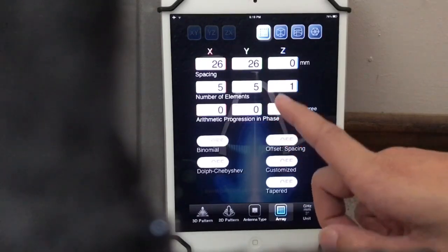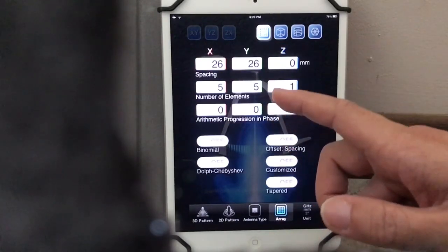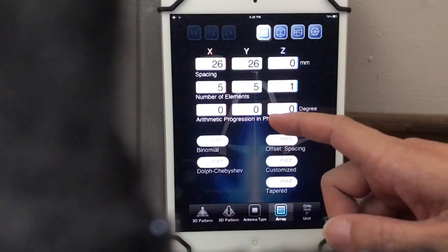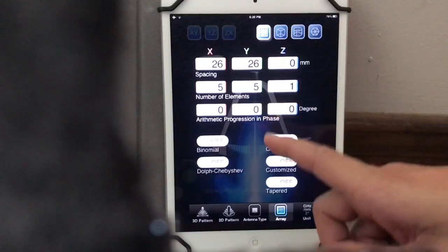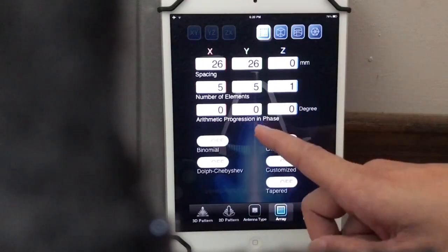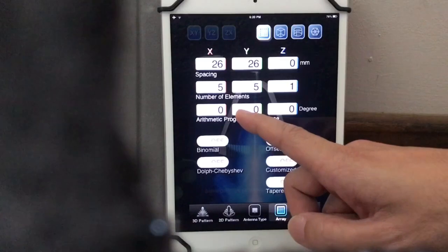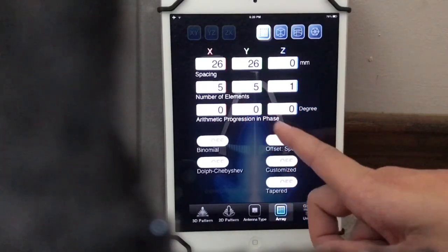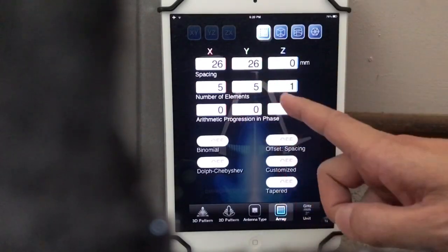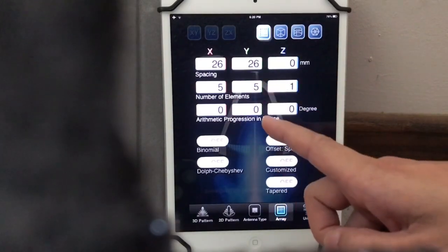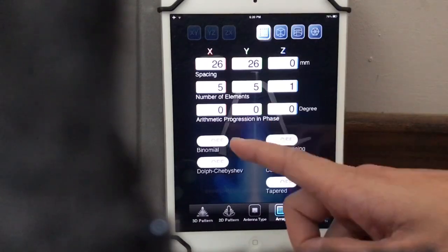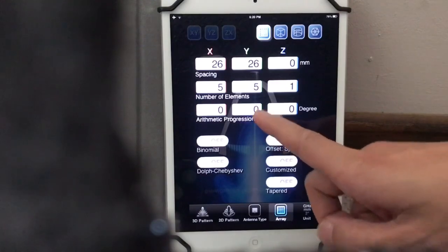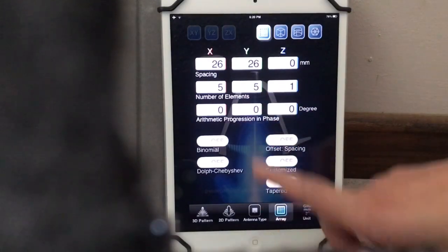So if you're doing beam forming, like you want your antenna to form a beam in a specific pattern. For example, if you want the beam to always sweep to the left, you could have delay. So by setting delay, it's like a phase shifter. You could delay each antenna in your array, and then the delay will cause the resultant beam to steer to the left or to the right. And this is interesting if you're working on phase shifter arrays or phase arrays.